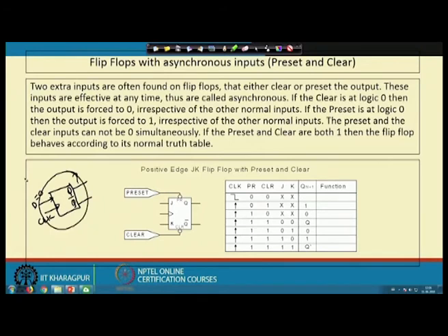If I make a circuit like this and switch on the circuit, then this Q and Q bar will pick up some arbitrary values, and from that point onwards, depending on the D value, it will go on operating, but the system behavior will become unpredictable. For the SR latch we have seen that we should not apply the pattern 1 1, but we do not have any control over that. We want Q and Q bar to always be complementary.